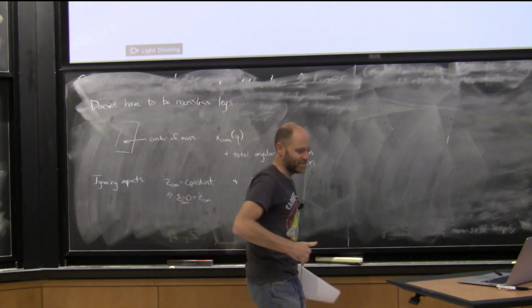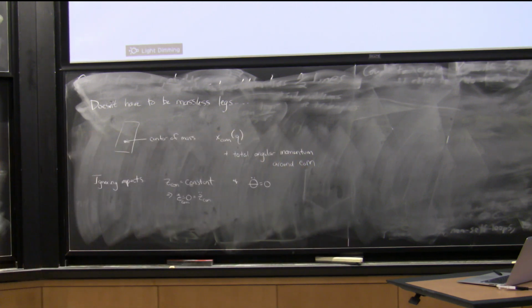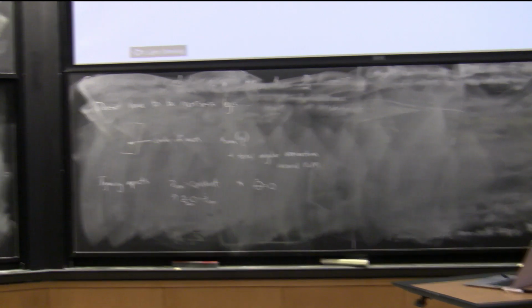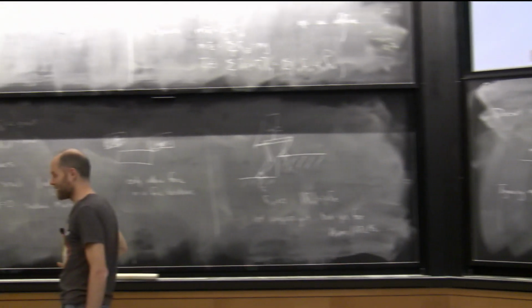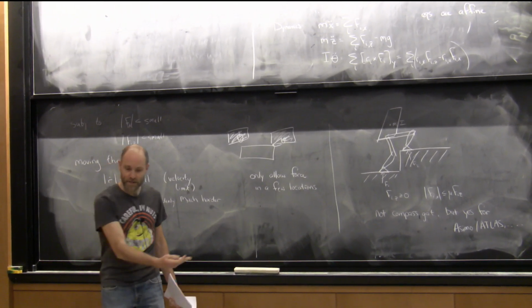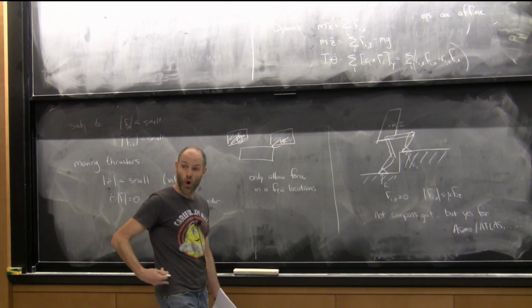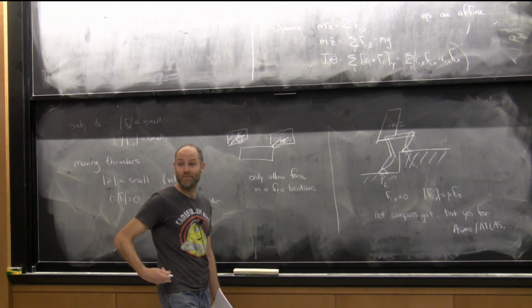It's the thing I hate. But if I'm willing to walk like this and I'm actually regulating my center of mass, which is a simple function of Q, so as my joints are moving around, I can certainly estimate it and try to regulate it. If I manage to keep that completely flat, then I've imparted no energy into the ground when my foot came down. So there was no collision.